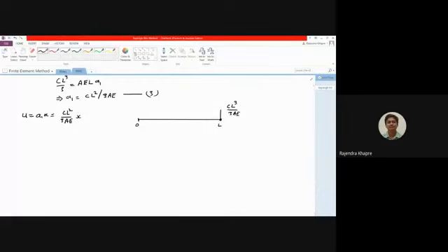So we can simply join with the help of a straight line over here. You can see that as the value of X is changing, your displacement is continuously increasing, and the maximum value of displacement will be C L to the power 3 divided by 3 times AE. Okay, so this is the variation of the displacement.